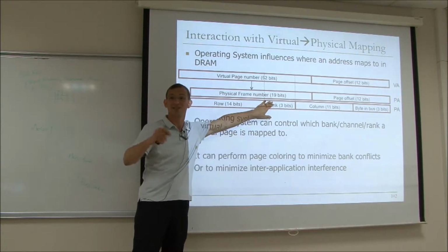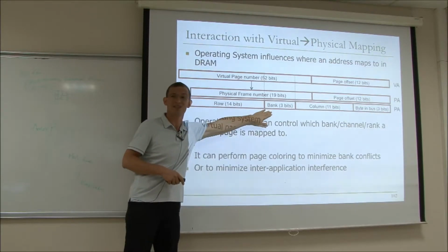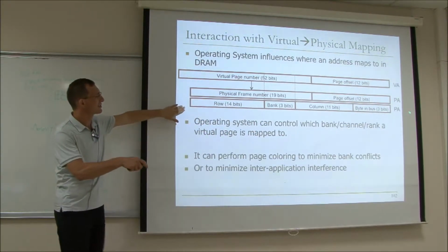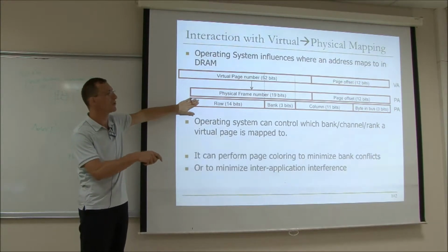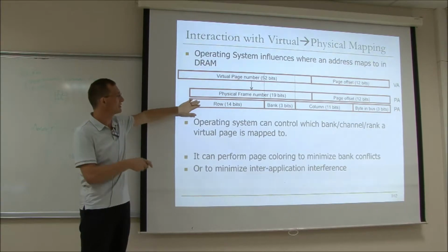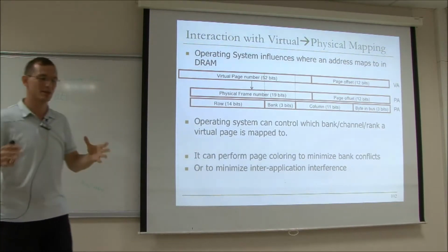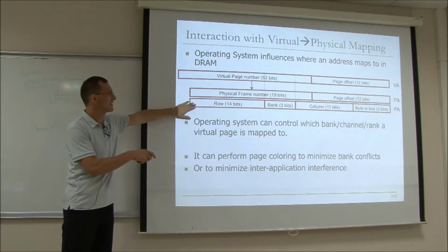This is the page coloring that we've seen earlier, except at the memory level. That way, you can reduce memory interference. One big problem today is this structure is really not known. It's not exposed to the operating system. Let alone the operating system, it's not even exposed to the processor designer. So actually, the memory controller has this, but it's not exposed anywhere.